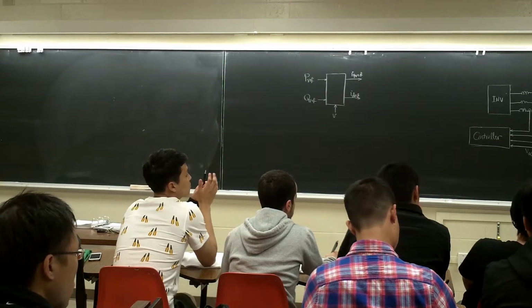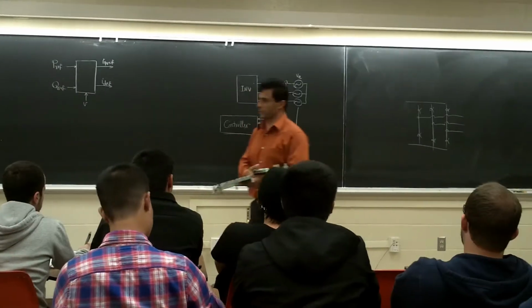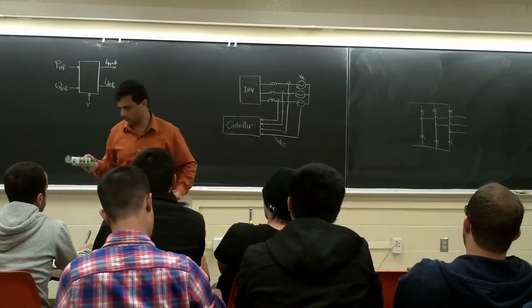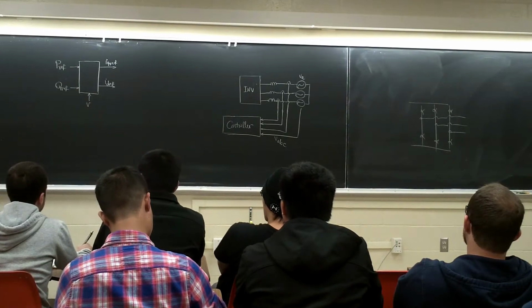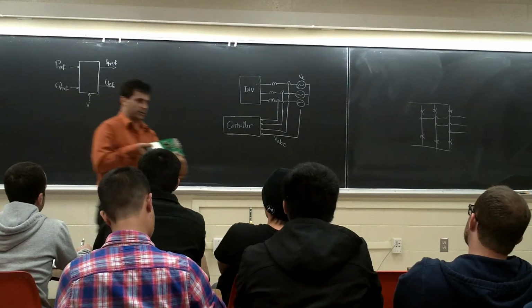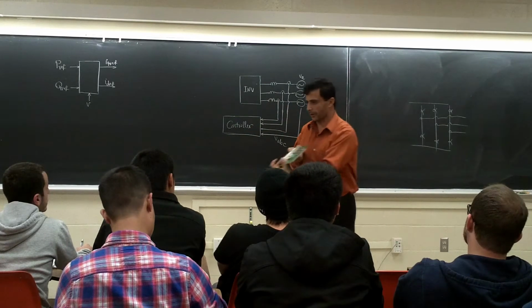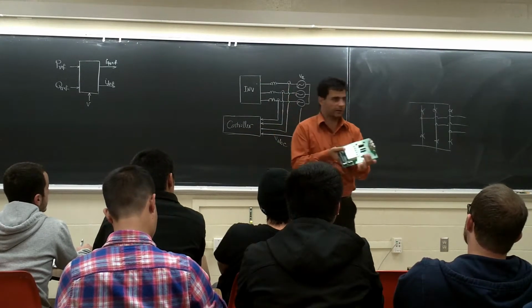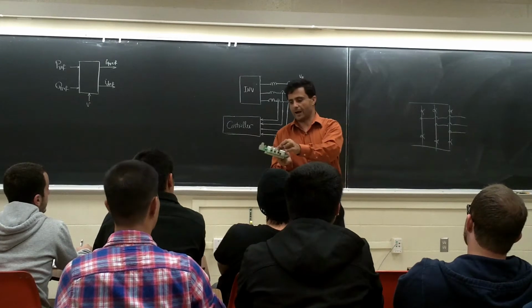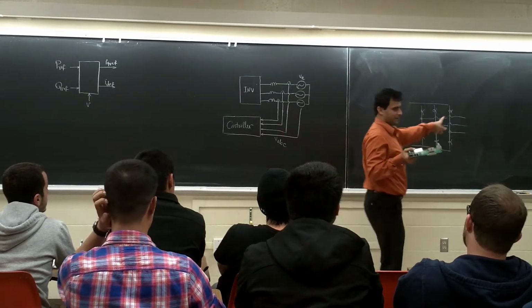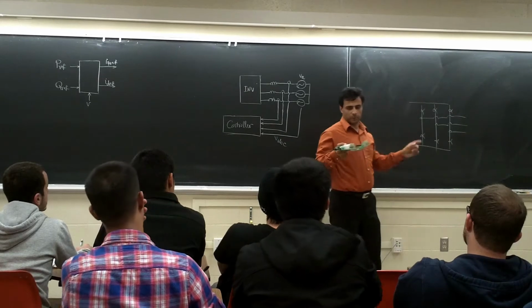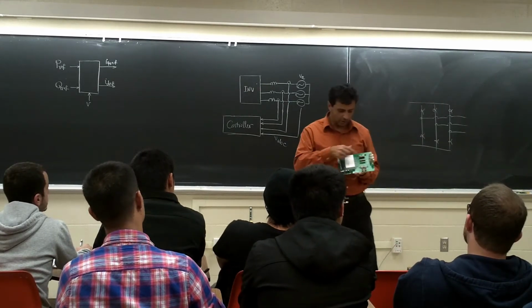And each cross is a switch with an anti-parallel diode. And if you look here, this is a DC connection. You connect your DC, whatever, battery, solar, whatever you want. You connect it here. This is a DC connection. These three are AC outputs, DC inputs.